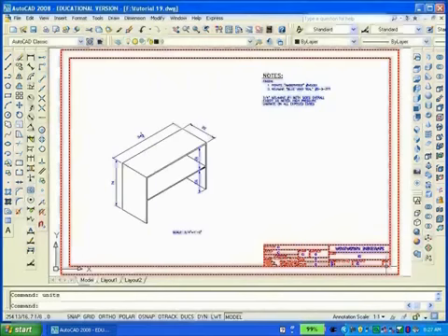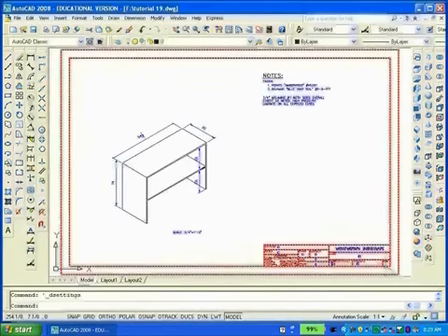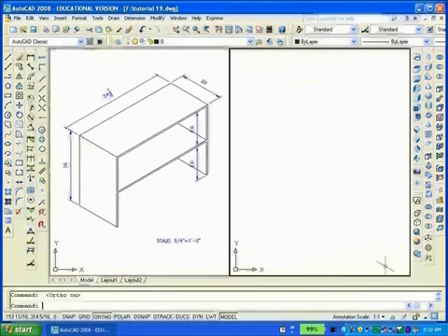Next, on the Tools menu, click on Drafting Settings and select the Isometric Snap. The isometric snap makes it possible to toggle the crosshairs using the F5 key. That key allows us to draw on different planes, as you will soon see. Now I'll move into a split screen to make the drawing. Toggle the F5 key to set the crosshairs to draw the top or plan view.